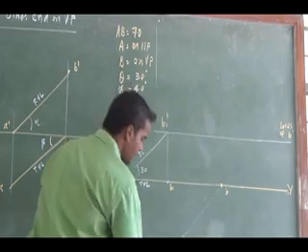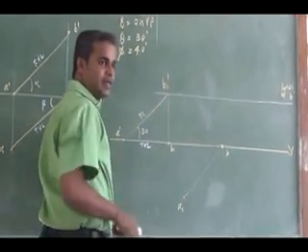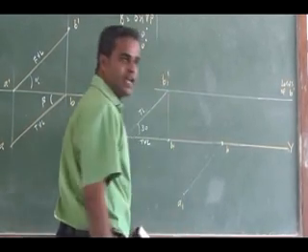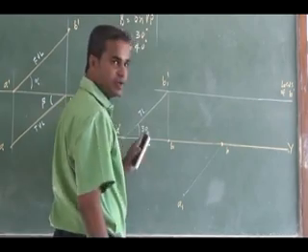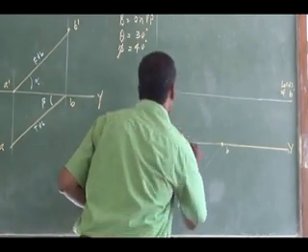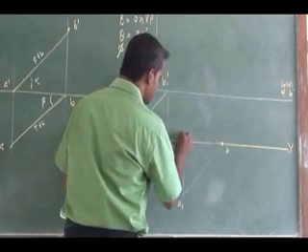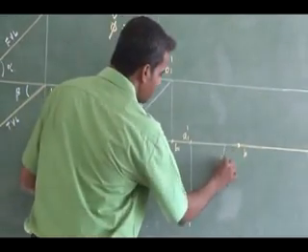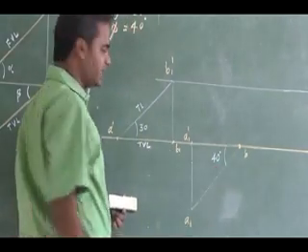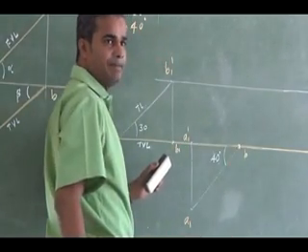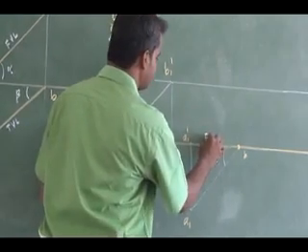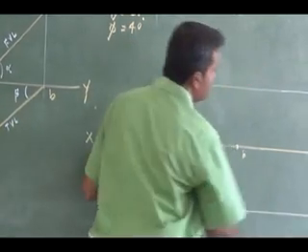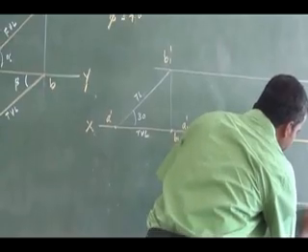So this will be my A1. This is another top view location of end A. Okay, we don't know. So that is A1 I am giving. Right. So this I will project to the location. This will be A1 dash. Right. From this second step, this is my 40 degree inclination. What is A1 dash B? It is my front view length. So from this second assumption, I know this locus. I have got the locus of B.